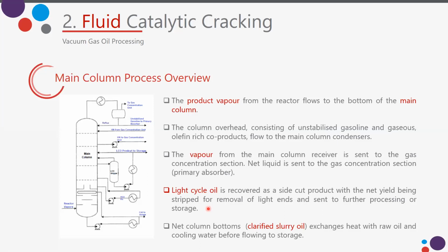But I mean after burning. After burning, and produce flue gas, we have 5%, no? After burning, in the catalyst, you have less than 0.05% of coke in the catalyst. Okay. But this 5% is the yield if you take into account the feed to the unit. But we will also see that we have, on the same basis, something that they call the delta coke, that is the coke in the spent catalyst minus the coke in the regenerated catalyst. Okay, that's okay. Thank you very much. Okay.